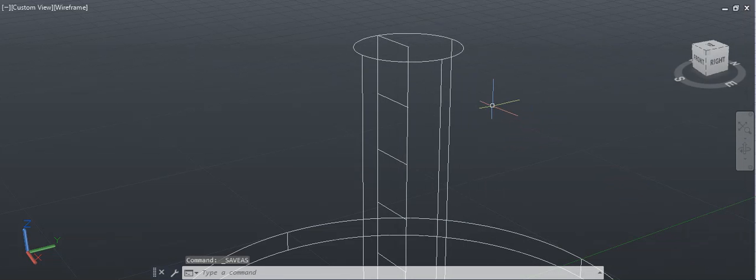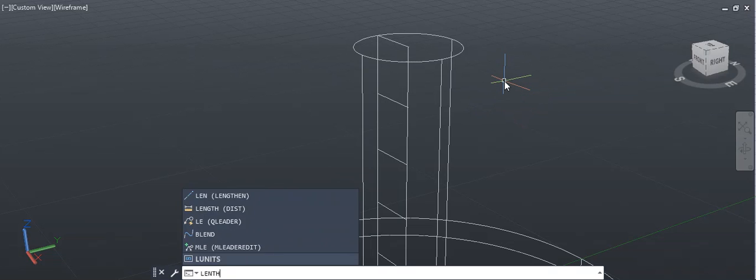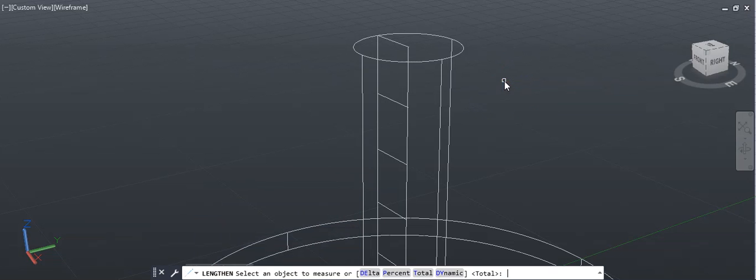Okay. Now, the next thing to do, I'm going to select each line and lengthen it. Lengthen, believe it or not. Hard to say it, but lengthen literally extends the line. So I'm going to type lengthen, L-E-N-G-T-H-E-N, enter. Oh, I just spelled it correctly. How cool is that? Lengthen, and now it says select the object.